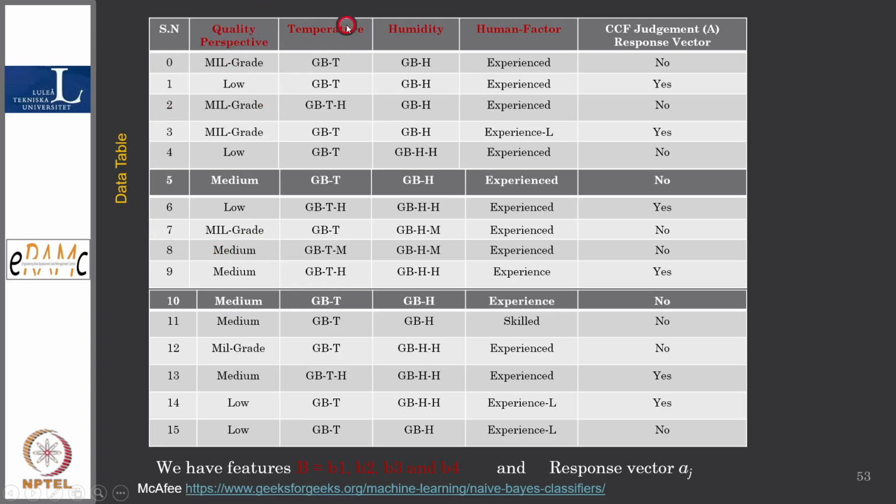Now, electronics get affected by, we know, temperature, humidity, and human factor. Human factor maybe in calibration, installation, and repeated in-out maintenance, so it gets affected. Now I think I have not given these abbreviations, so please listen very carefully. It is ground benign: the instrumentation rack where the electronic board was installed is ground benign. Ground benign means 22 degrees centigrade temperature and humidity 55%. That is the ideal condition for electronics to operate.